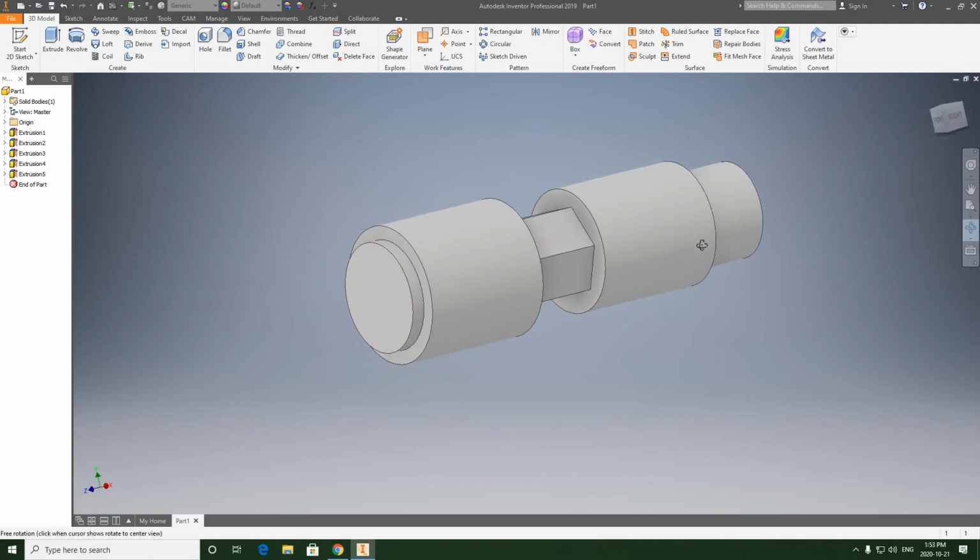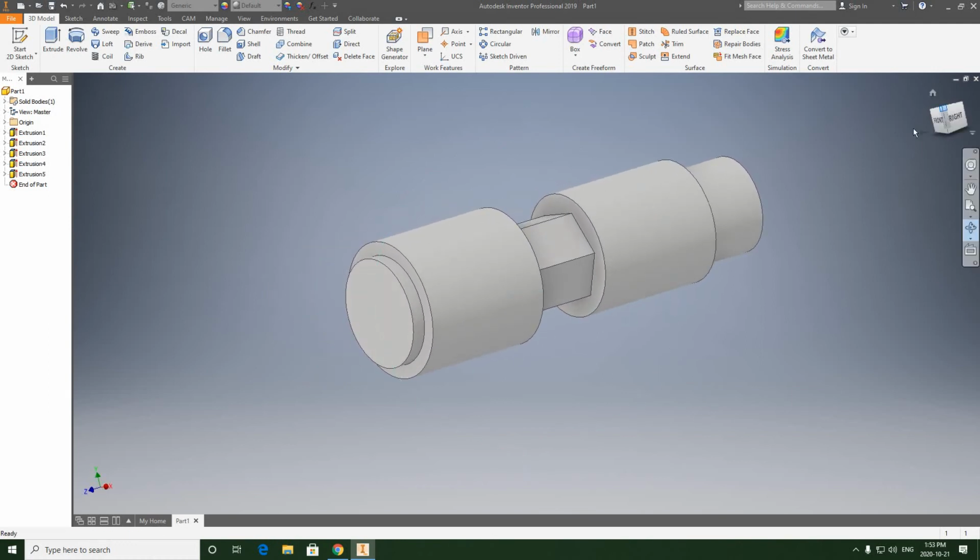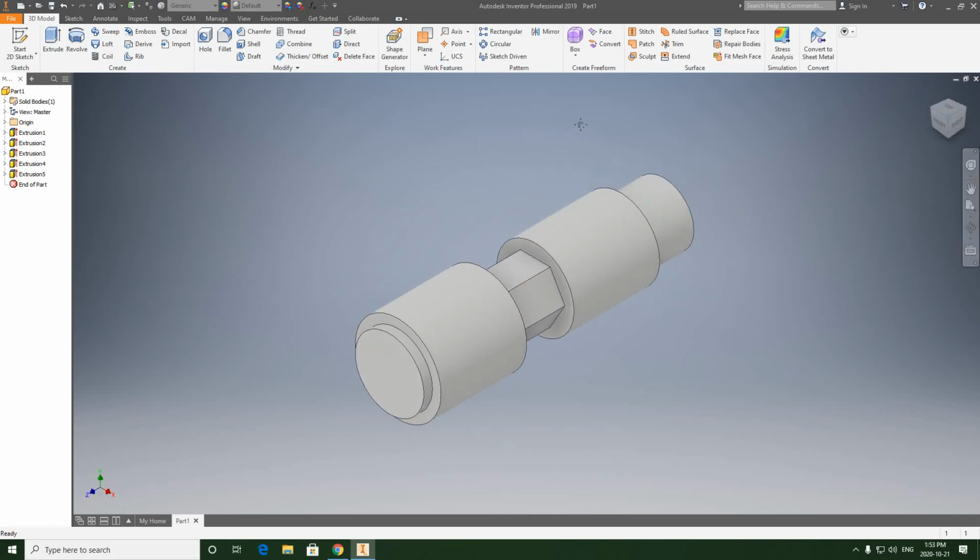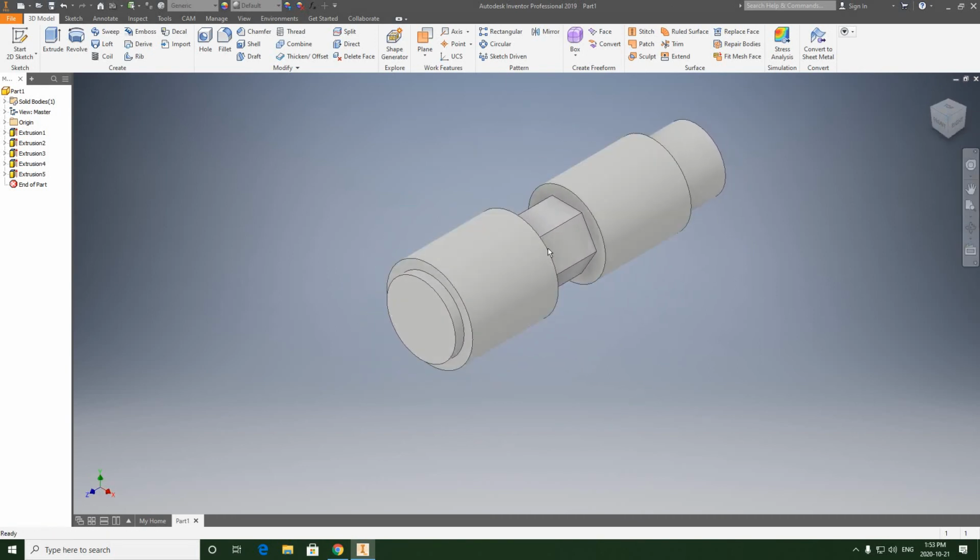Now, this is something new coming up, right? We're going to create a simple loft. So what we need to do is create a work plane and offset it from this face. So what we're going to be doing is creating a plane from this face and offsetting it out, and we're going in a positive direction of 2 7/8.